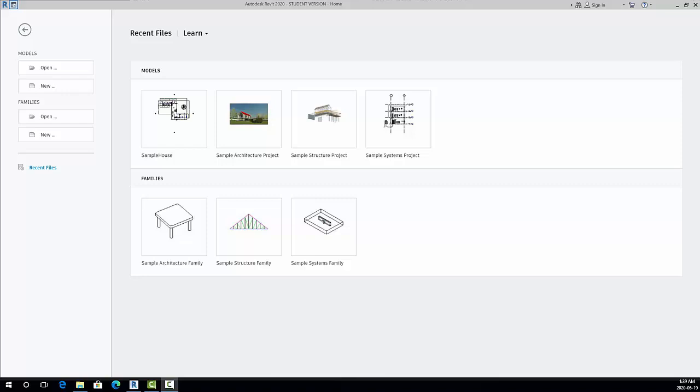The more efficient your template is set up for your project types, the more efficient your work session will be. The less time you'll spend downloading things from other locations and things like that. So template files are actually a fairly important aspect in using Revit properly. Whenever you start a new project, you do have to select a template file.